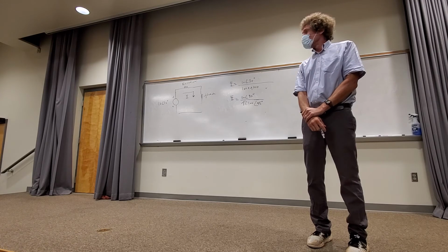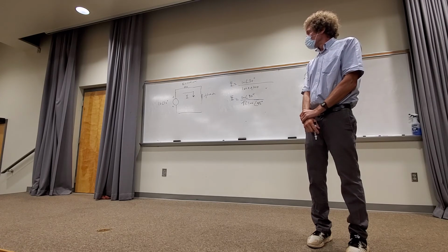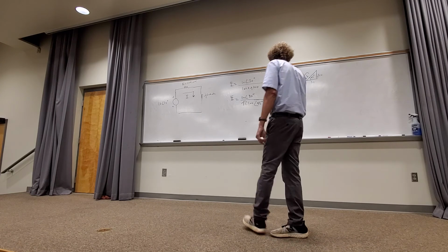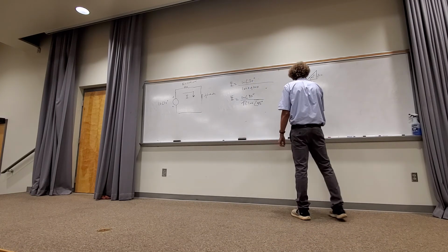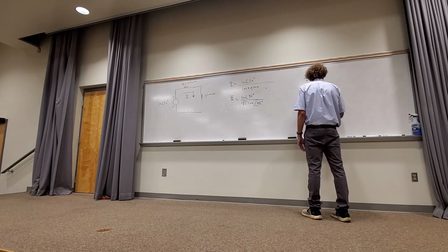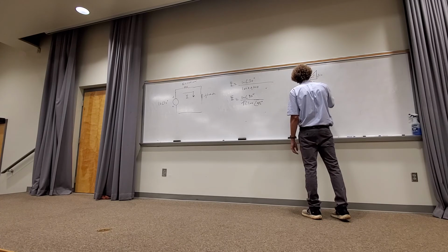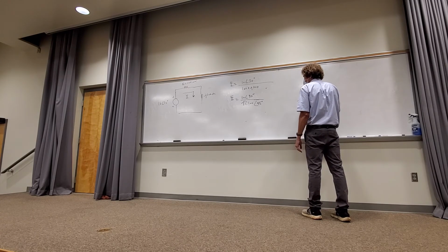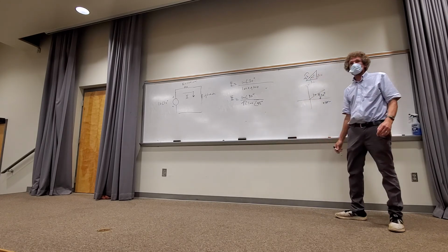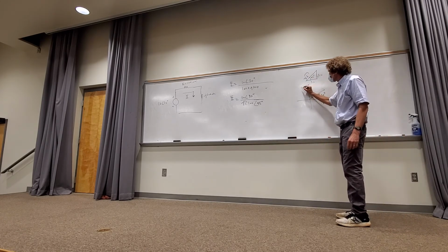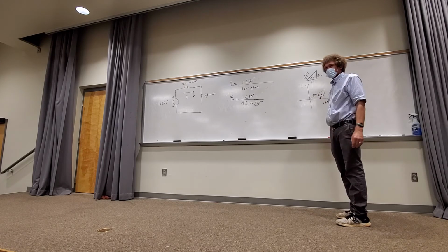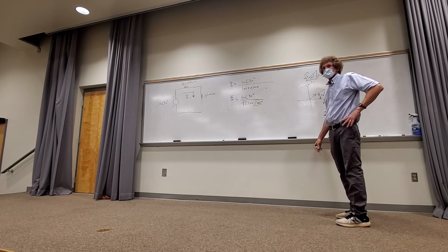Okay, but like, what about if we're talking about the voltage here? The voltage at 30 degrees, if you wanted to actually graph it, if this was the real axis and this is the imaginary, this would be 10 at an angle of 30 degrees. That's what that means. It's in the complex plane. So this is the imaginary or J-axis. This is the real axis. And then X-axis is the real values. Okay.